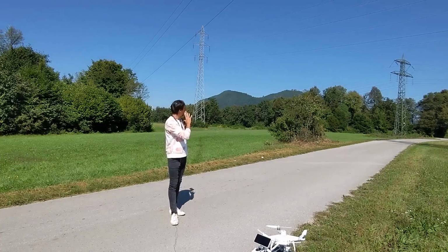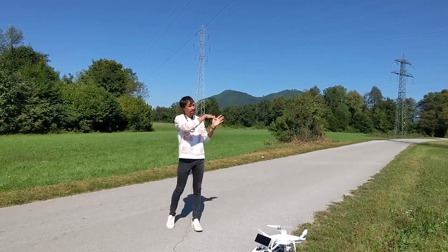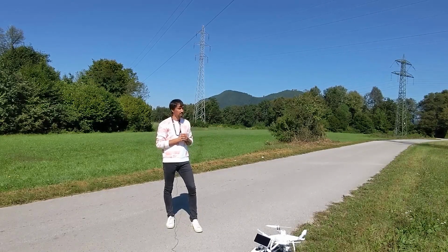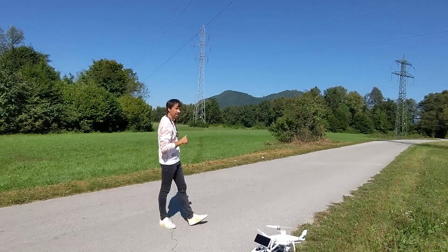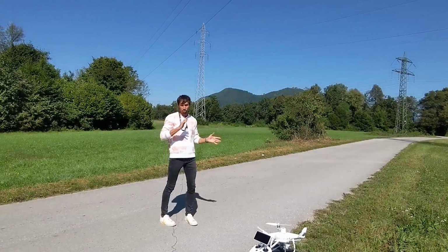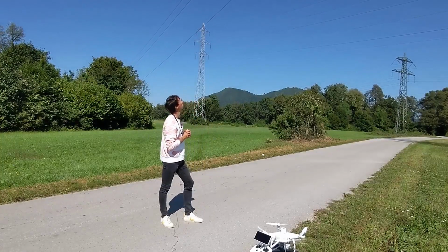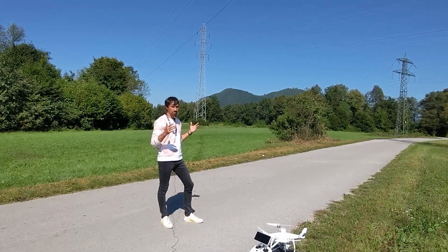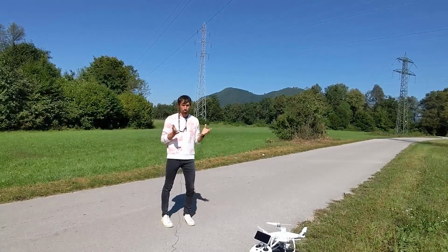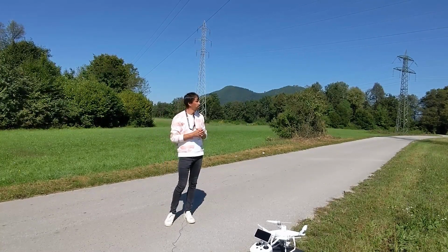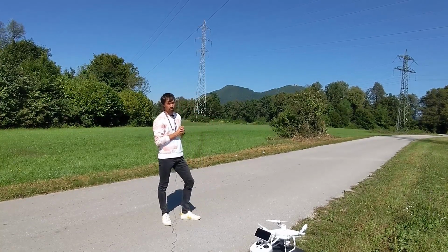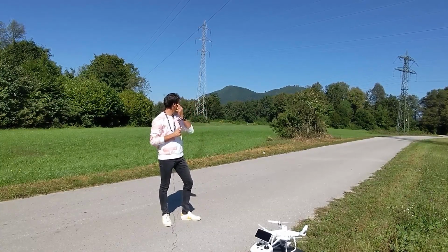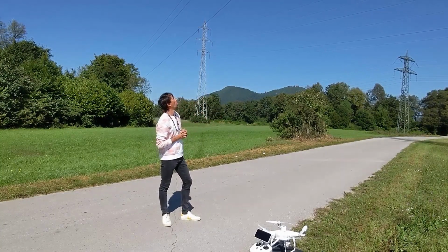So this project we mainly do to extract the cables and how high they are above the terrain, or how far they are from the vegetation, if they need to cut the vegetation or something like that. So this is a pretty useful tool to monitor it. You can usually do this 10 kilometers per day or something like that with this equipment and 3Dsurvey. For this purpose we will capture 1 kilometer with 2 big power lines and then power poles, and in addition there are a few more power lines beside our area of interest.